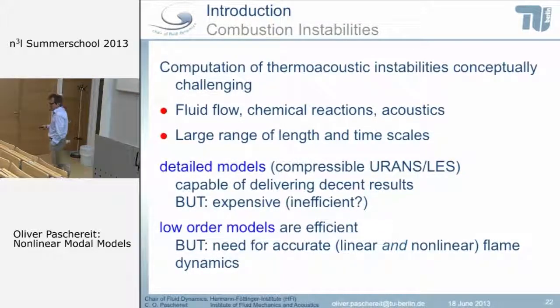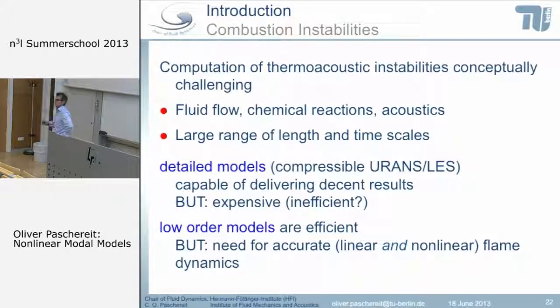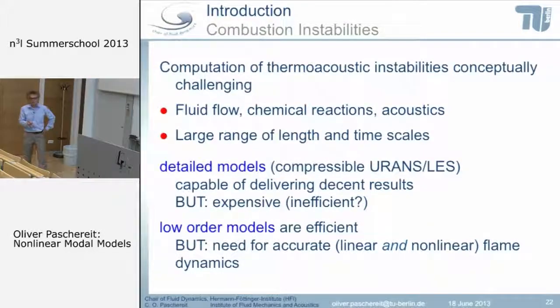And you can try to use detailed models, like, for example, large eddy simulation. Even if you want to predict the acoustics, you can do it compressible, but it's very expensive. And although we see that, like at Surfax, they try to model full combustors, it's still a very, very expensive thing and takes a long time to come to results. Low order models are more efficient, but then you need an accurate description of the flame dynamics. And this is, for example, what we can get from flame describing functions, from measured flame describing functions.